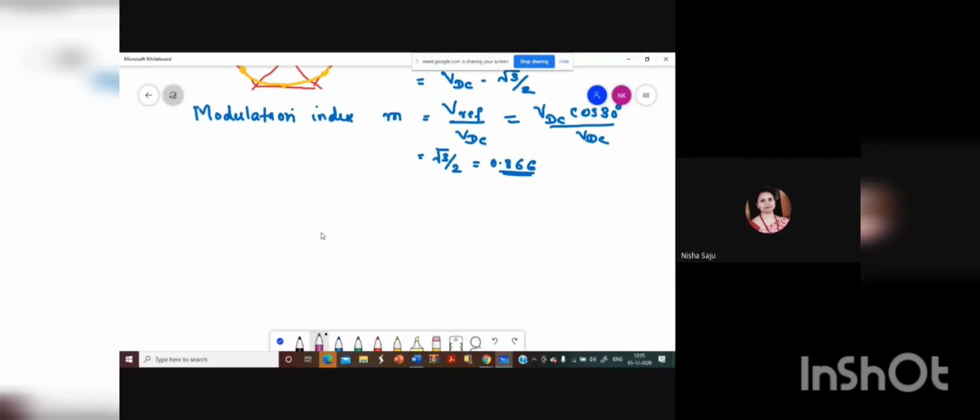That is the aim. So for that, what you have to do is take an alpha beta structure. In alpha beta, if you are having a 3-phase system, that 3-phase system has to be converted. This is your 3-phase system. This is your A, this is your B, and this is your C. So this three-phase system has to be converted to a two-phase system. Two-phase system in the sense that it should be an alpha beta, that is again a rotating plane, and that should be displaced at an angle of 90 degree. Why are we going for this? To make the three-phase system analysis easier.